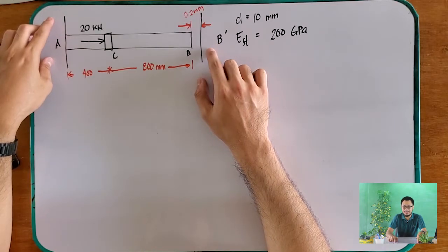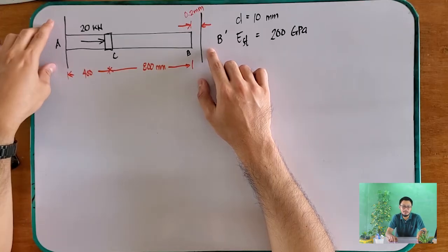Because we don't have any forces that are oriented on the y-axis. Can we use summation of moments of this one? No, because the forces are collinear with each other and also on our moment axis magtagbo pod sila. So we can use only your summation of forces along the x. And therefore, this one is a statically indeterminate axially loaded member.